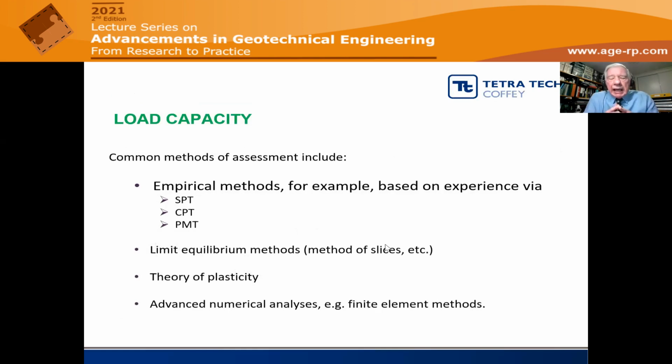Now, coming on to how we assess load capacity, there are a number of common methods that are essentially empirical. These would be, in my categorization, category 1 methods based on experience, and methods that use such parameters as the standard penetration test, the cone penetration test, or the pressure meter test.